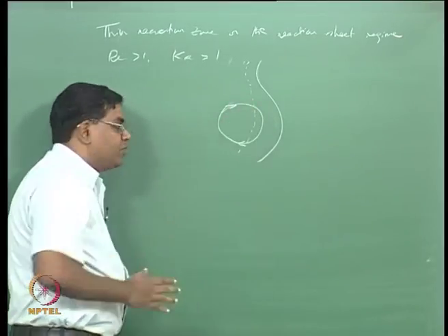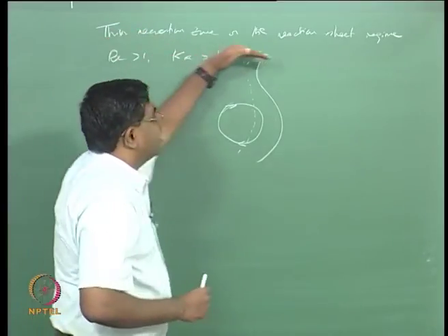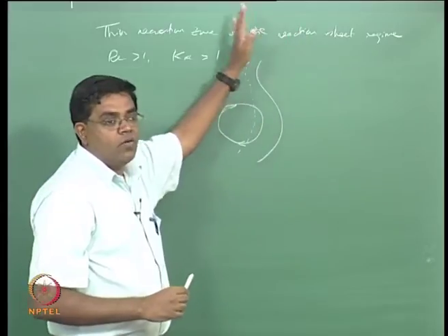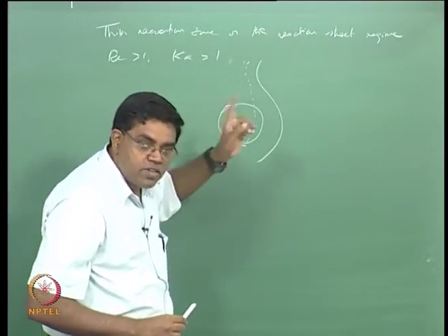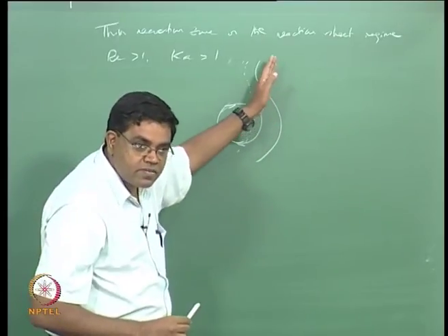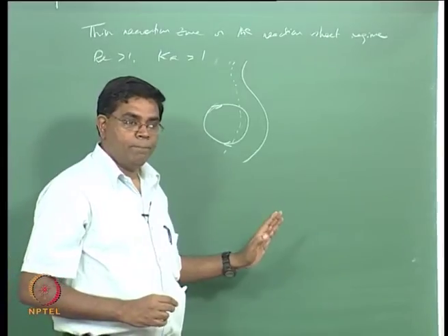That's essentially what's going on. So that's the reason why we are calling this a reaction sheet regime. That means all that we can talk about as a characteristic of the original premix laminar flame, the remnant of it, is only the reaction zone. The preheat zone is now marred, right.